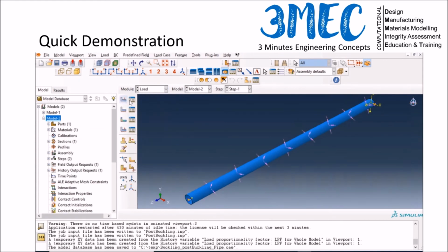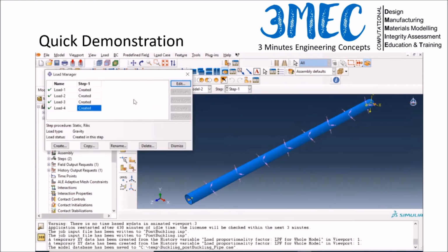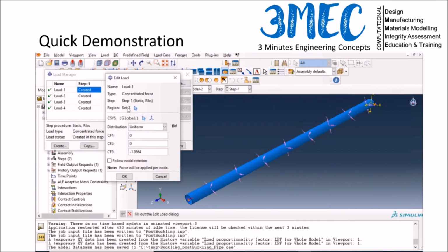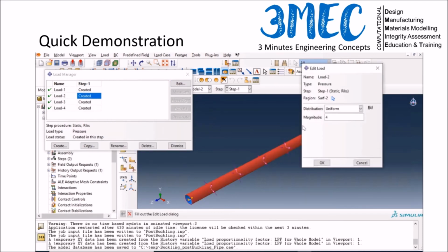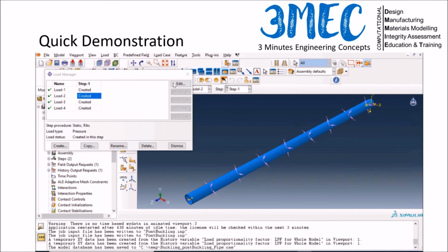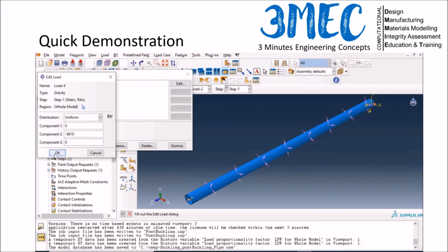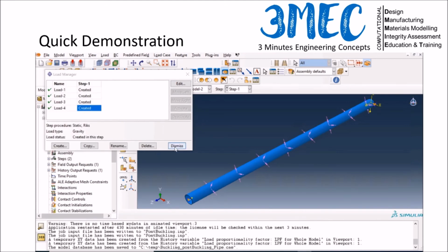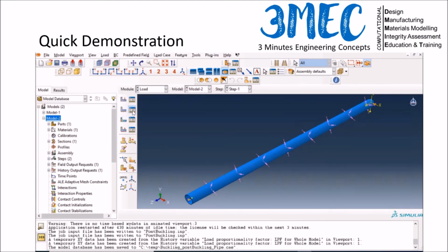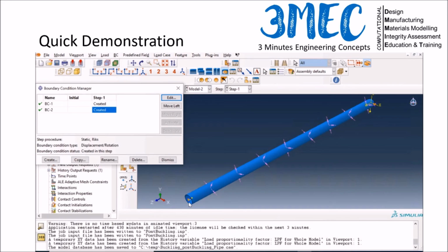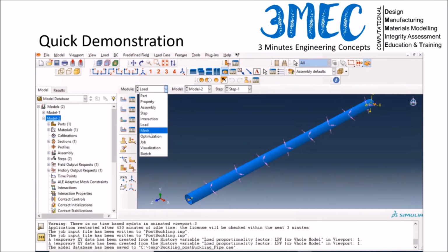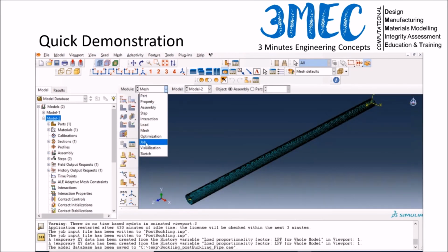All the loading and boundary conditions will remain the same except for the effective longitudinal force, because I'm going to use now the value of the eigenvector for mode 1, which is this one in this case. The rest of the material property and the rest of the boundary conditions I don't touch, because effective longitudinal force is the most critical parameter in every case and can be varying throughout. So that is done. Boundary condition, lateral direction, and also fully encastered or fixed on the other end. Anchor point, mesh is the same, and then I run the job.